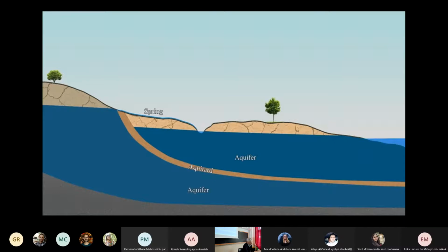And in the video, they said two important things that I want to emphasize. First, the recharge of the confined, of the deep aquifer, is slower. And we discussed already the importance of flow to ensure sustainability. If the recharge is lower, you can understand the use is less sustainable, because it may take thousands of years to get the aquifer recharged.